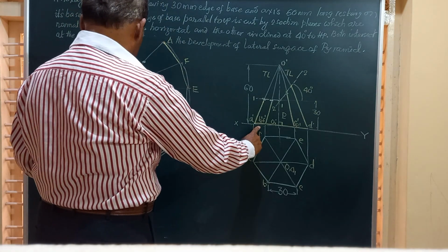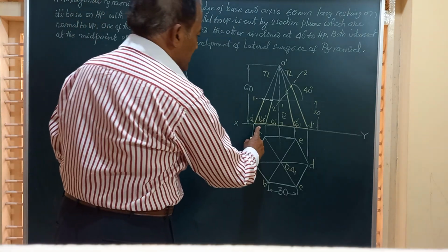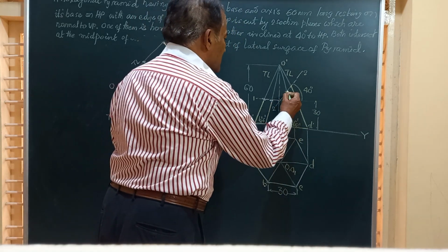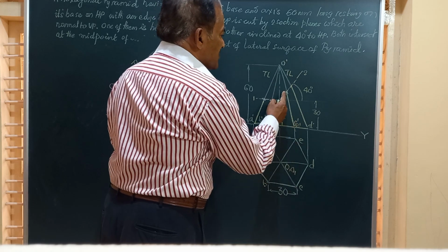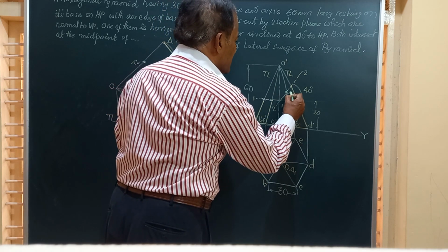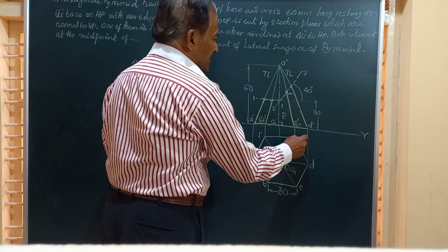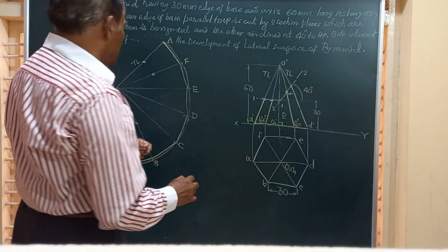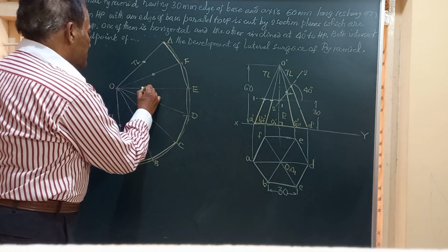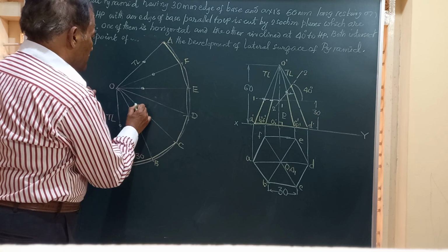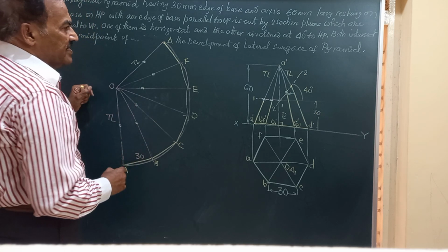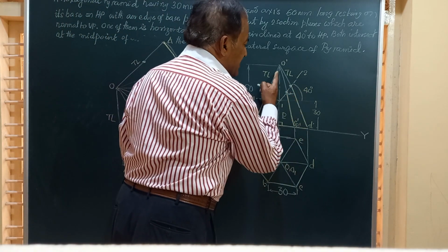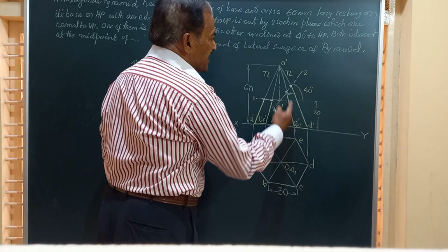OA we have marked, OB we have marked, OF we have marked, and we have got here OC and OE cut at a height higher than this. So this is not the true length. Transfer that to the end generator or the end slant edge. Obtain that measurement on only OC and OE. So this is OC and this is OE. OC and OE will have the same height. Finally friends, here the section plane 2 is cutting the true length generator O dash D dash at this point.